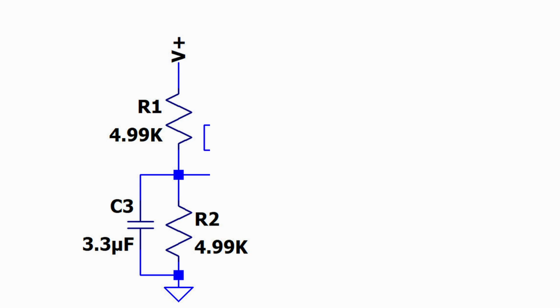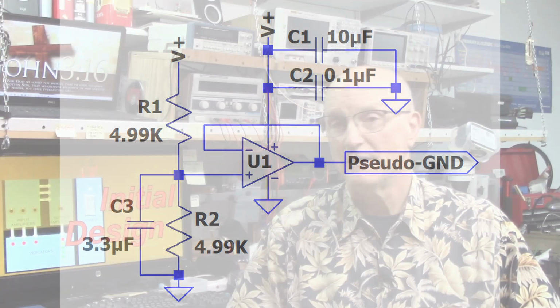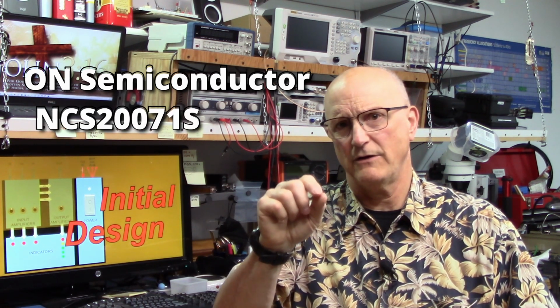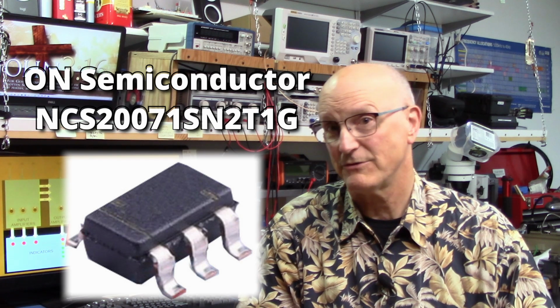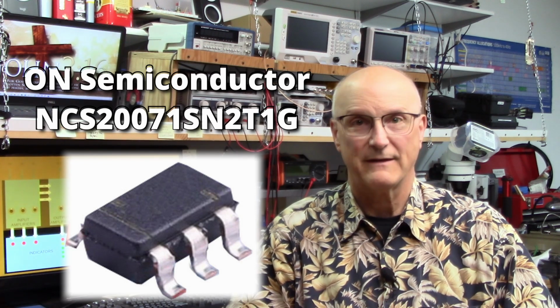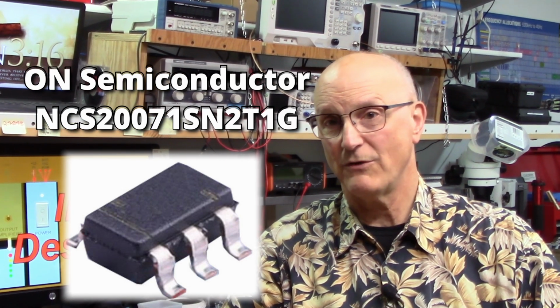The resulting voltage is the input to a non-inverting buffer amplifier stage using a single op amp. The choice of the op amp really isn't critical. I mean, you could use an on-semiconductor NCS20071SN2T1G. It comes in a nice SOT23-5 package, easily soldered by hand. At DC, it has a very low output impedance and will provide that VCC over 2 voltage that you need while absolutely following the power supply voltage variations.